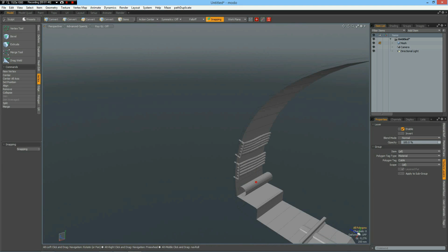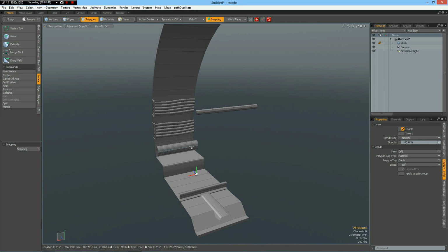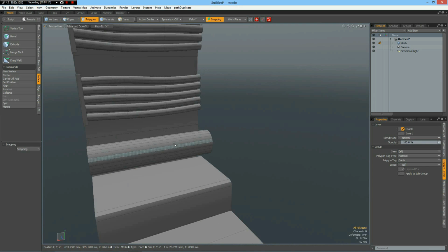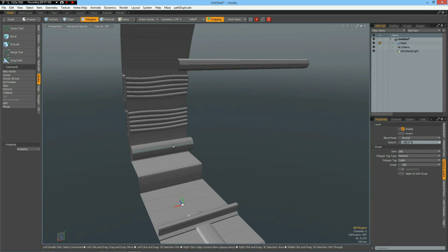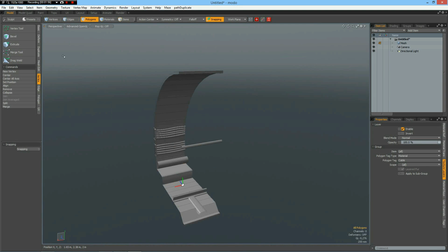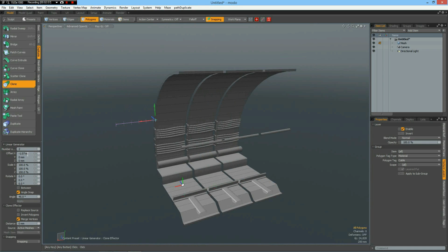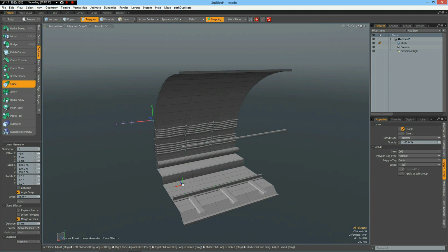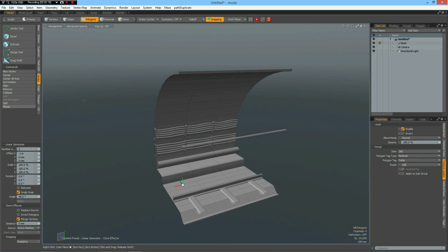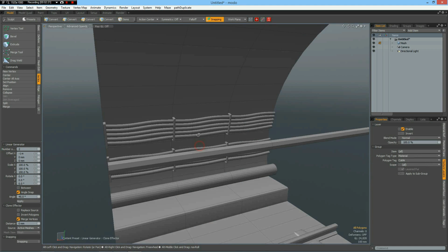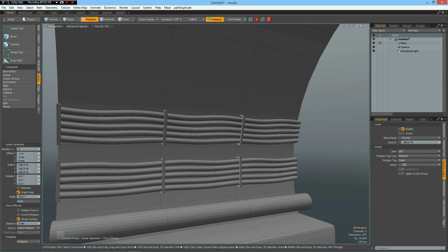Okay. Next I will extend the supports, so Shift X, and move them to about here, like so. Good. The next thing I want to do is have a support for the pipe every 3 meters. So I need 2 clones of this. Go to Duplicate, Clone, number of clones 2, click in the viewport and bring this out, -1 meter again, -1 meter. And let's check if the vertices have merged. Automatic, no. Good.